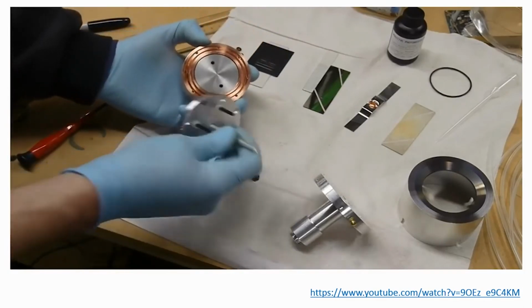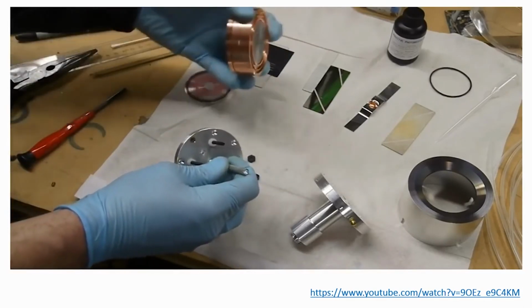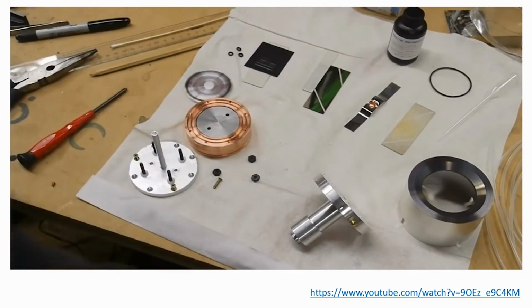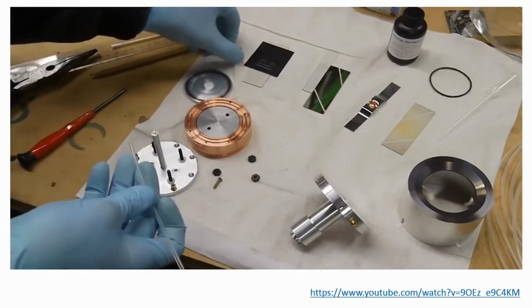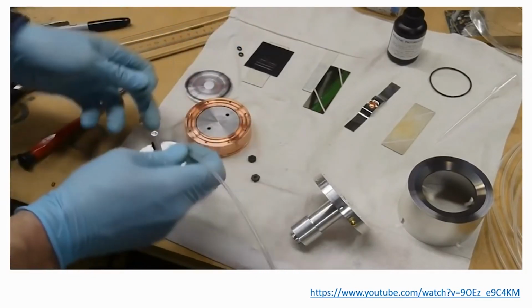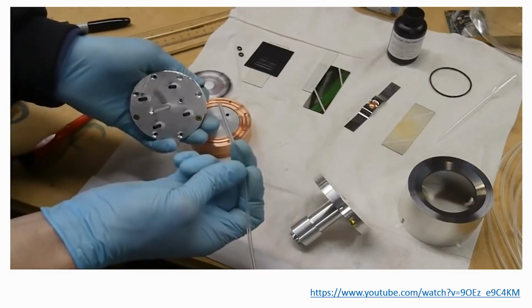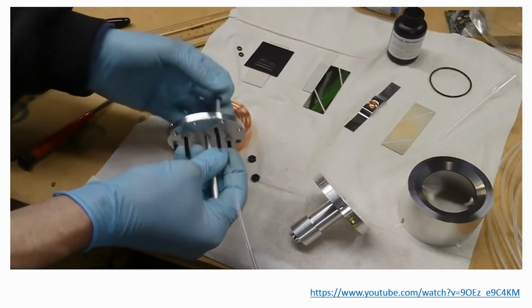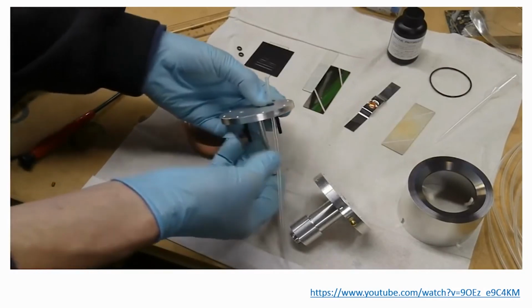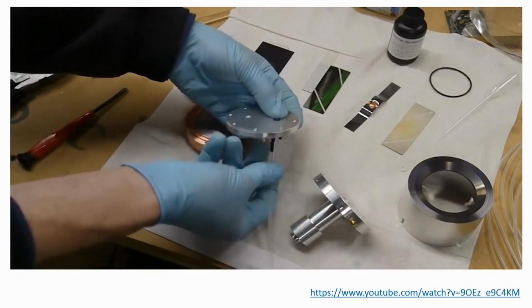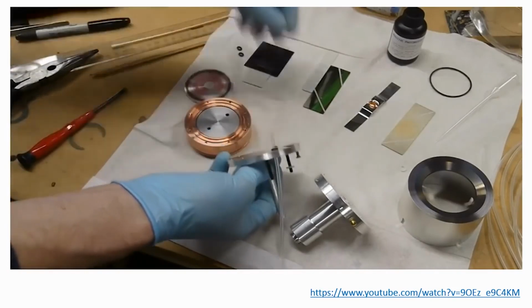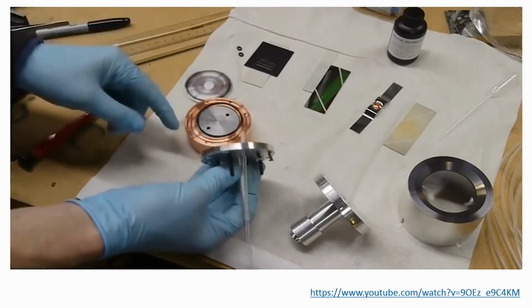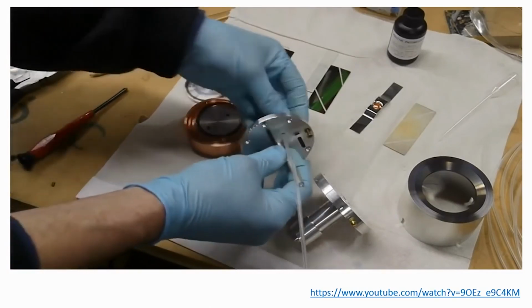I've also got some holes in here for a cooling system, which unfortunately I didn't have running yet, hence the cracked disc. The idea with that would be, this is a sort of Teflon hose. It's actually a plastic called PFA with an O-ring on like this. The hose can be sealed up to this, and then with an O-ring in the right spot here, this whole thing closes up and I can actually pump water through the copper block.